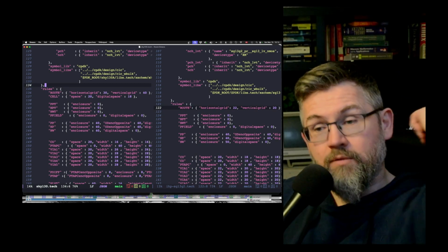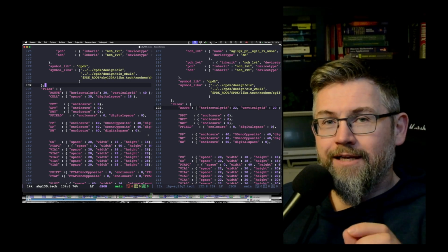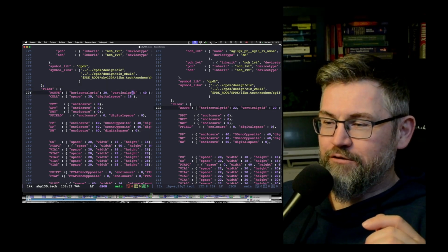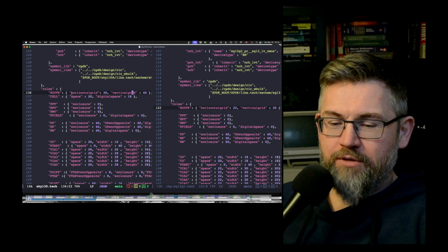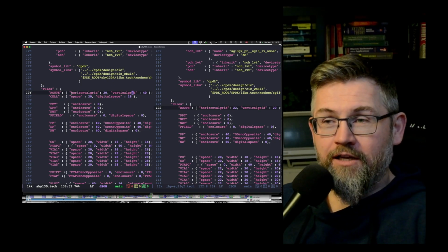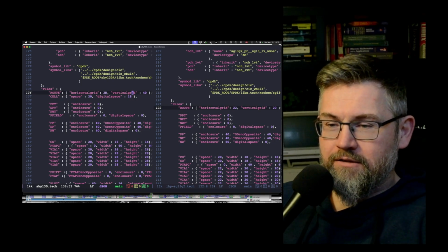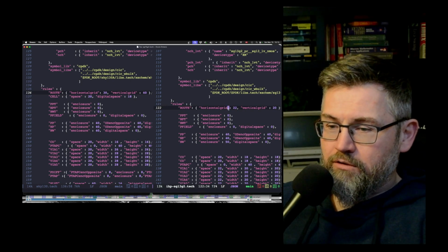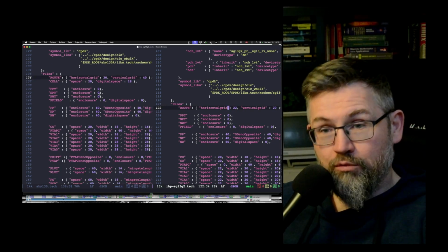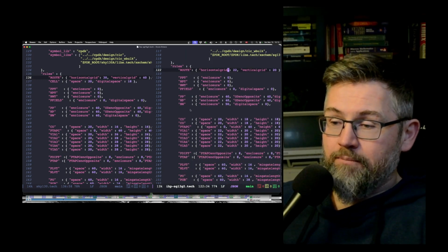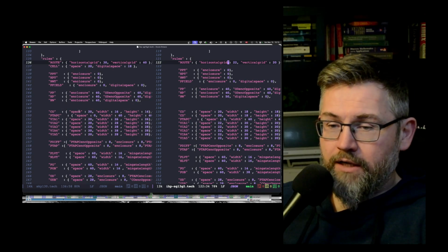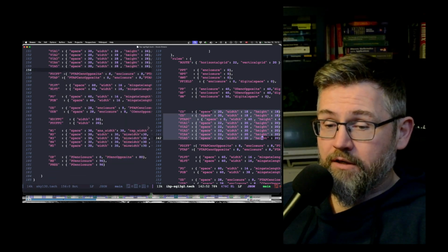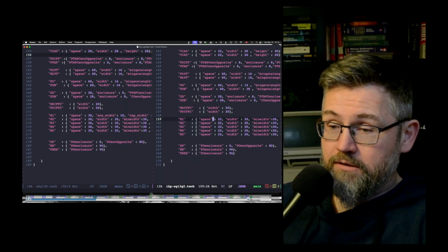For the transistors, as we'll soon see, there is an ASCII art description of the transistor. And there's really only one parameter that describes how to translate the ASCII art into a real thing. And that is these two parameters here, horizontal grid and vertical grid. So you can see that those are different between the two technologies. Many of the rules, these are the design rules, they're the same. But things like contacts are obviously different because that's very technology specific, and things like metal routing is very specific,